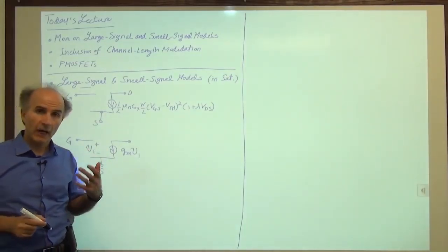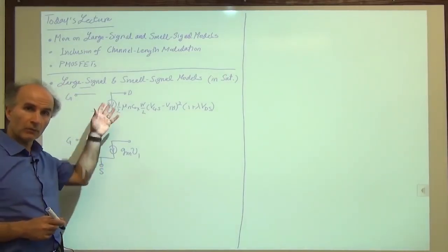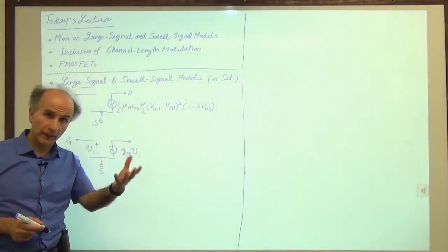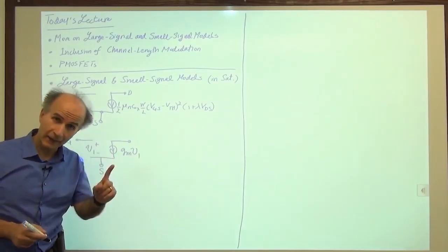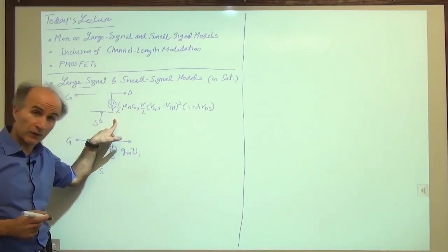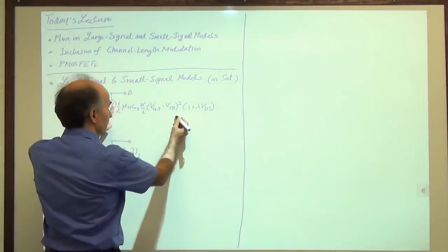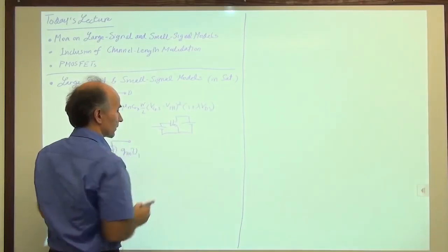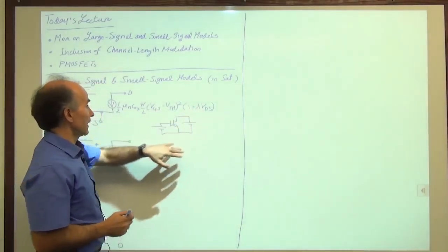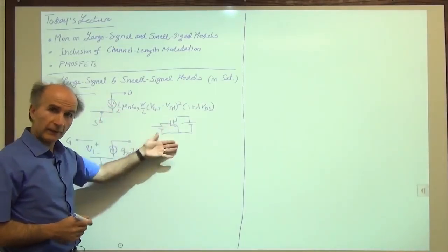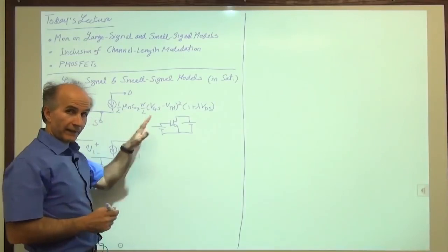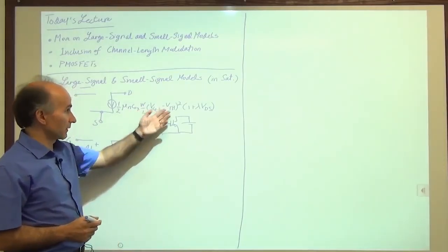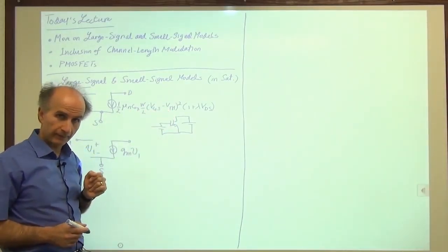Now, if you remember from last time, our analysis usually has to draw upon both of these, because when we start looking at the circuit, first we have to see what bias voltages and what bias current it has. For that calculation, we still have to use this model, even though there's no signal in the circuit. So this model would apply to a situation like this, where we have a constant battery between the gate and source, another battery between drain and source. So we know these batteries, we know VGS, we know VDS, we can go ahead and find the current. And that gives us all the bias conditions of the device. Now, that's done. We have the properties we need. We can find gm, because gm can be calculated in terms of VGS minus VTH or ID, all the equations that we saw before.